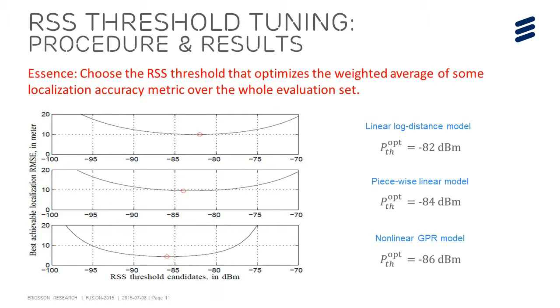In our work, the localization accuracy metric is chosen to be the best achievable root mean square error formulated with the aid of Cramer-Rao bound analysis. This sets a lower bound for unbiased position estimators that are mostly considered in the signal processing society. Alternatively, we could also use other bounds, such as Barankin bounds and the Bayesian type bounds.